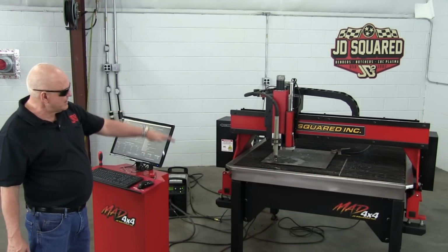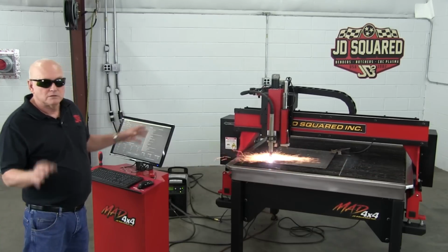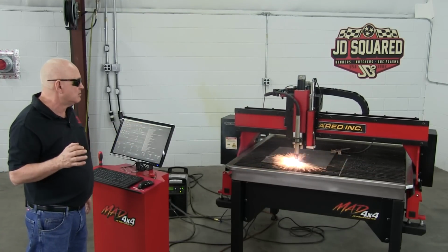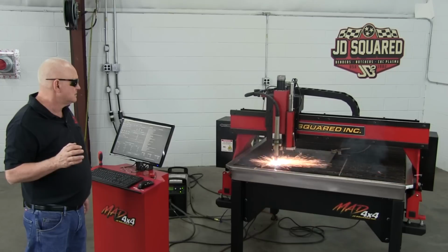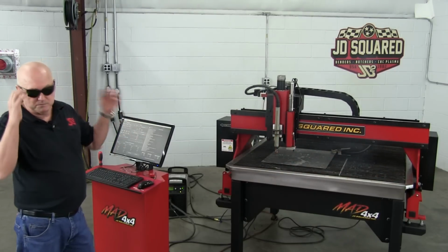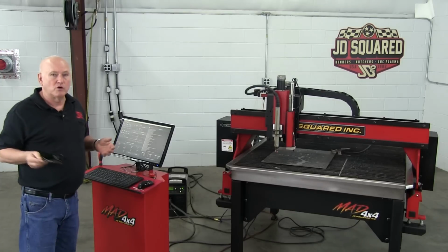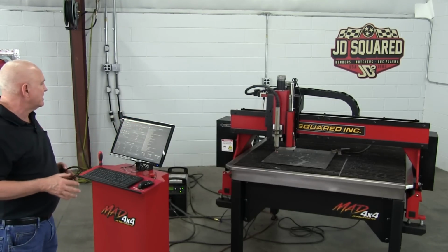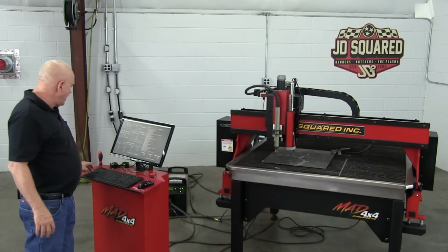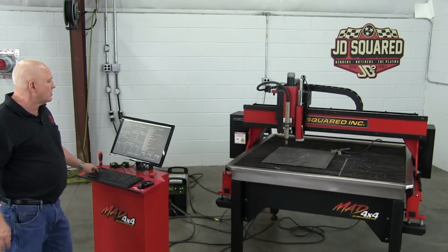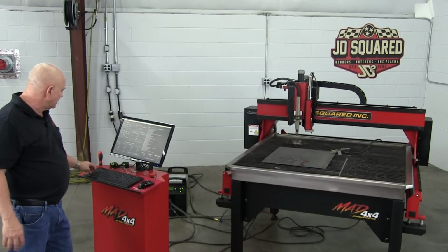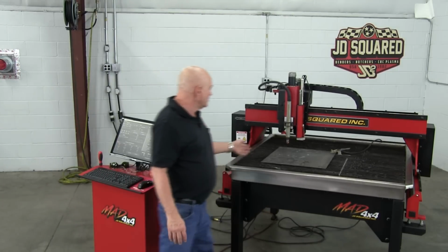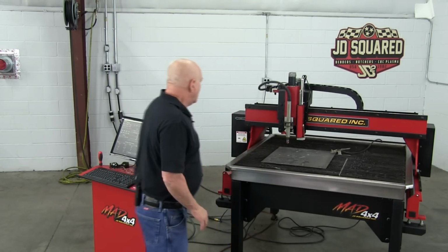See right here, she's probing down from 1 inch. In a minute, I'll show you where it will not probe from 1 inch. It'll probe a little more efficiently. Okay, at this point, we're done. Hypertherm has a delay when it turns off the gas to clean everything out. We're going to move the torch out of the way. Look at her splashing right there. Let's move it back over here where it doesn't splash. So there's our cutout workpiece right there.